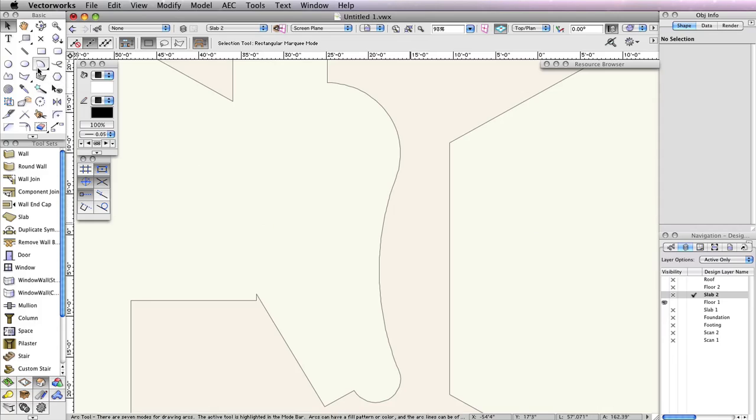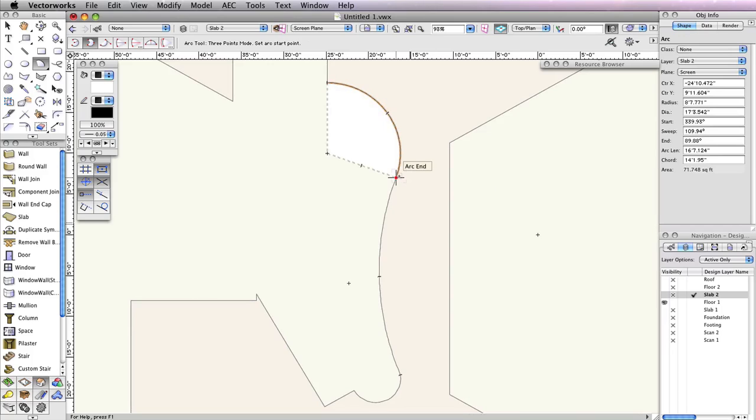select the Arc tool from the basic tool palette and enable the second mode. Click the topmost endpoint of the curve. Next, click the midpoint of that first arc in the curve when the cursor cue arc appears. Then, click the endpoint of that arc when the cursor cue arc appears once more to complete the arc. Complete this step 2 more times for the remaining 2 arcs that make up the curve. When you're finished, you should have 3 arcs.